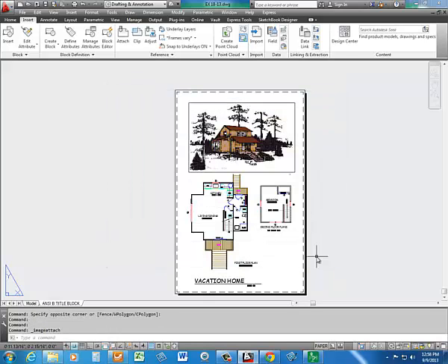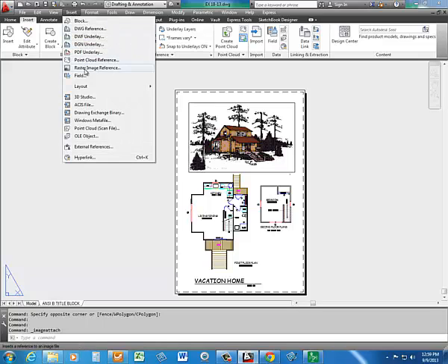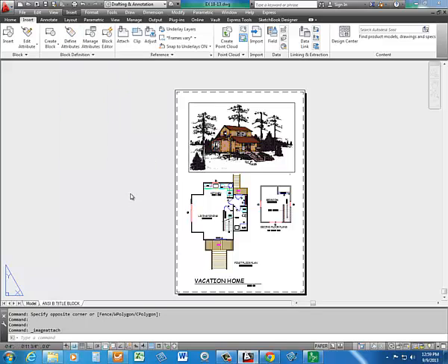And then you'll want to insert it as, let me retract that operation. We want it to be a part of the drawing. So here's a little problem with AutoCAD. If you do an insert raster image, it's a reference. Okay, so that will work and that'll be fine.